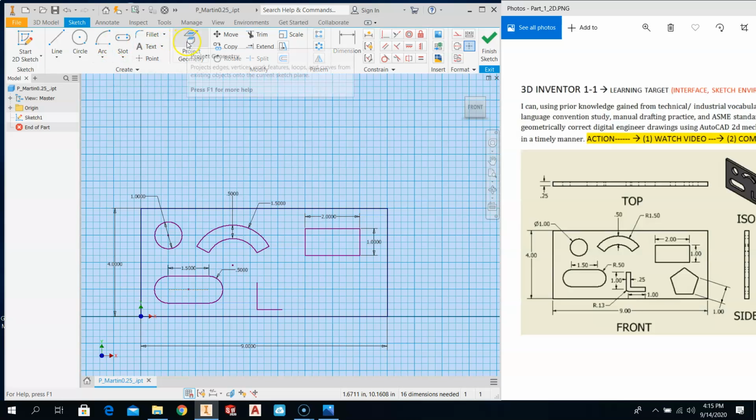So come up here, and that's just kind of a rounded sort of thing. So here's my fillet tool. I have a full screen, it's a little bit bigger. So 0.125, click here, and it automatically puts that in, and there's my radius. So I'm going to escape off that. Okay, and I'm going to drag this up a little bit. But again, this is why I had you, when we were doing our tolerances, give me 4 decimals. If you just did 2, you would see 0.13 here.